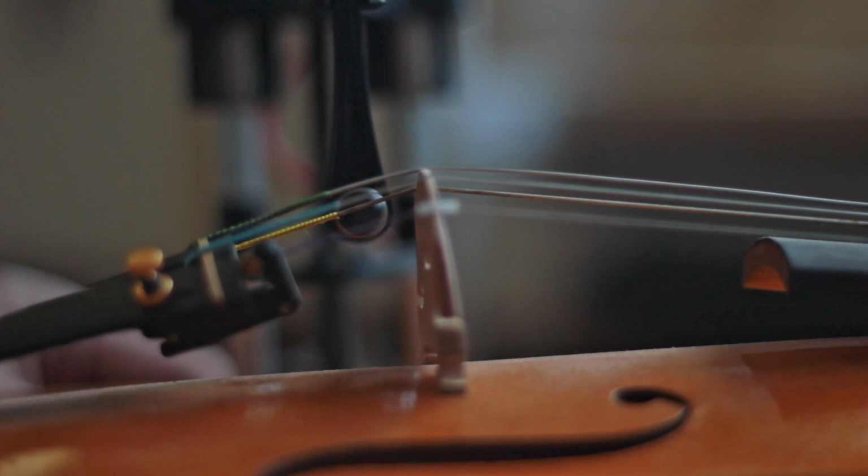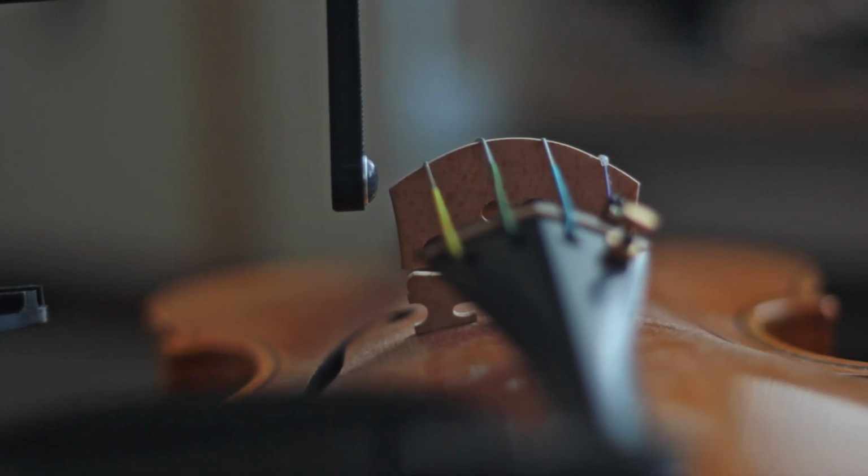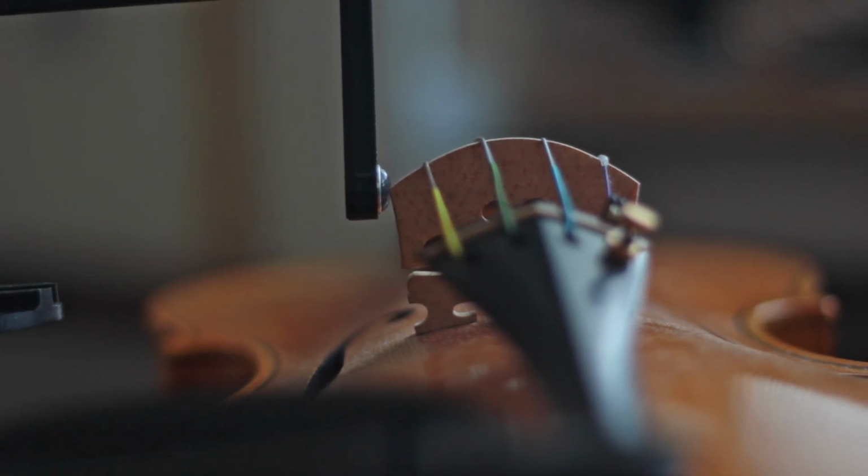Now technically, measurements that use a different convention are not incorrect, but they are hard to compare. The convention I will show here is established and has been chosen for good reasons, so I suggest you follow it too. I will bring the hammer in line with the upper bass side corner of the bridge. Then I will drop it slightly so that the contact point between the hammer and the bridge is about 1 mm below the upper end of the bridge.